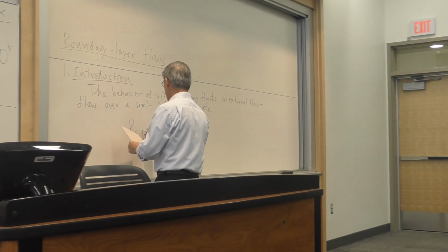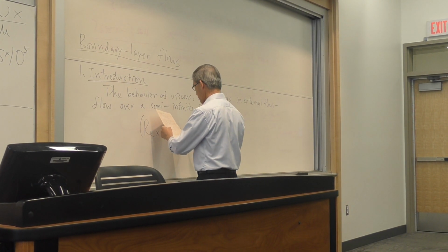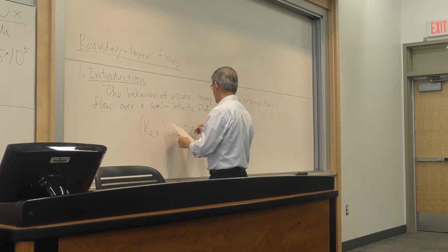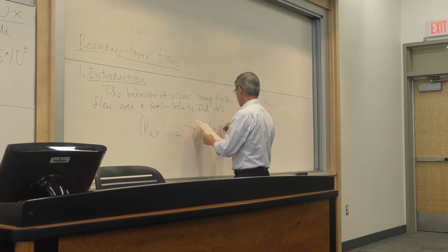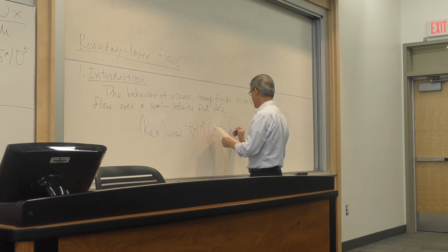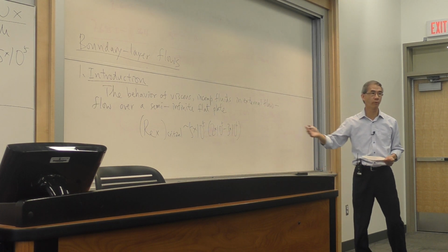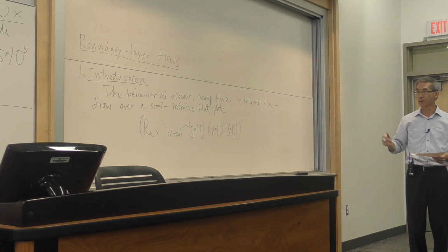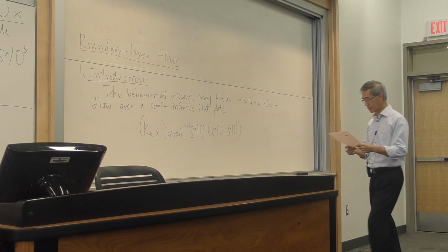Just like we experienced on the pipe flow, this so-called critical Reynolds number is not a magic black and white number, although for homework purposes, we take 500,000 to be our critical Reynolds number. But there's a whole range, all the way up to 3 million, and it's problem dependent, depending on what is called the turbulence in the free stream, the surface roughness, etc.